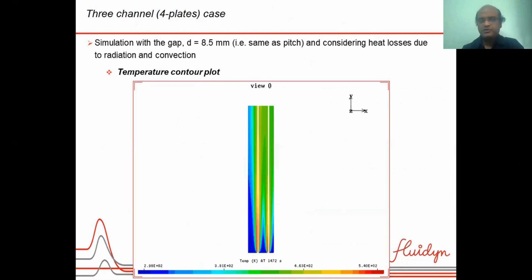So this shows the result here with two plates. This domain shows two plates. You can see the temperature plot. The hydrogen volume fraction is highest at the entry. So the reaction rate is the highest there, the heat release rate is highest, and the temperatures are also high there. And slowly it gets cooler, and gets dissipated in the whole gas.